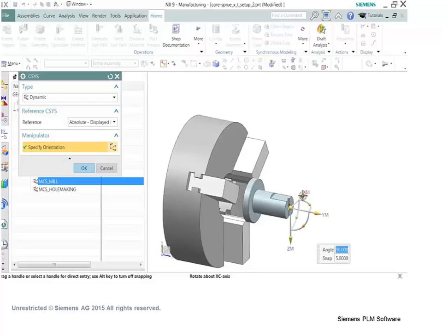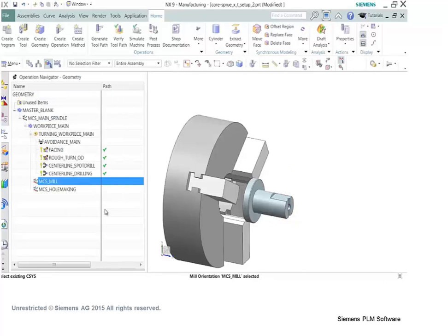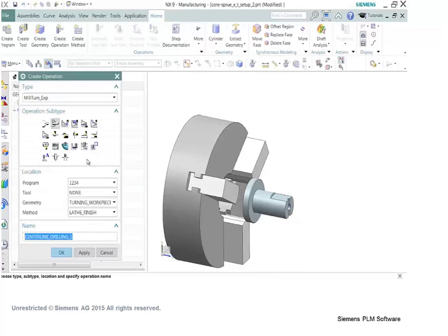And so we're going to flip which way we want Z. Put Z up. That's my XY that I'm going to use. I'm going to give it a clearance plane. We should probably do that. So we use floor and wall again. Again, it's really pretty simple. There we pick our tool. And what's the geometry we want to work on?